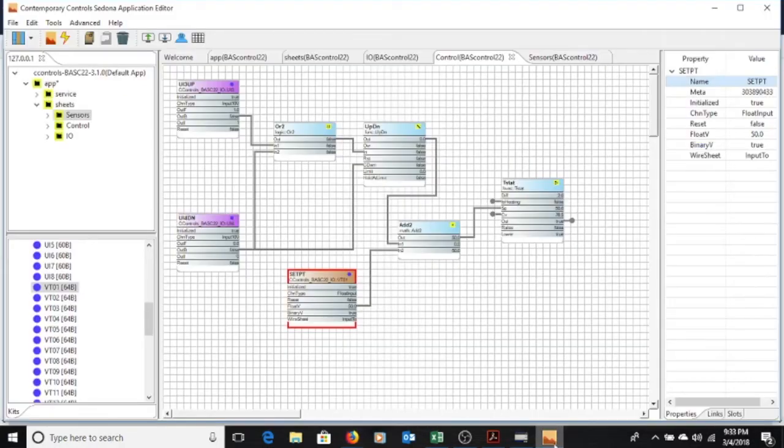I'm going to go to my controller. So again, the virtual point is very useful, I think, from an education perspective on how you can get students to interface with all of this. Now, don't get me wrong, wiring and what you'll be doing, it's wiring to universal input, you have to physically wire it, and do not forget the common point. If your controller wires and stuff are all going green and things are messing up, you pretty much got the common wrong.